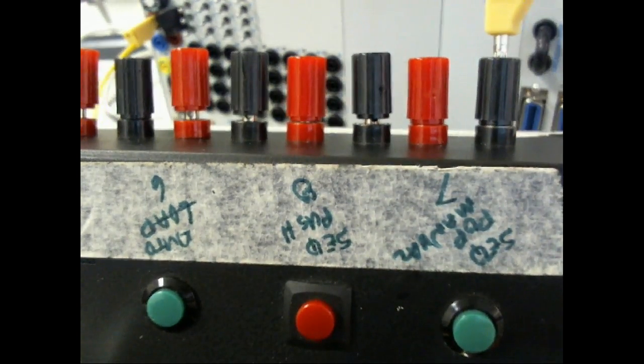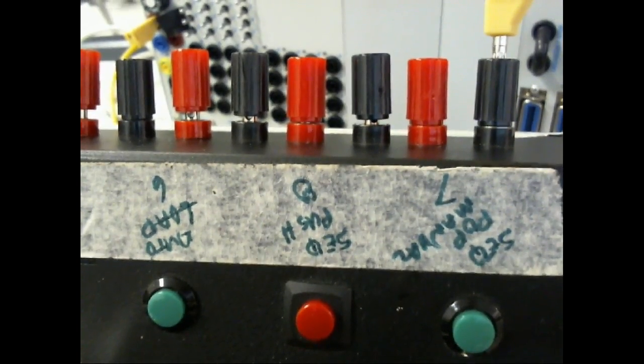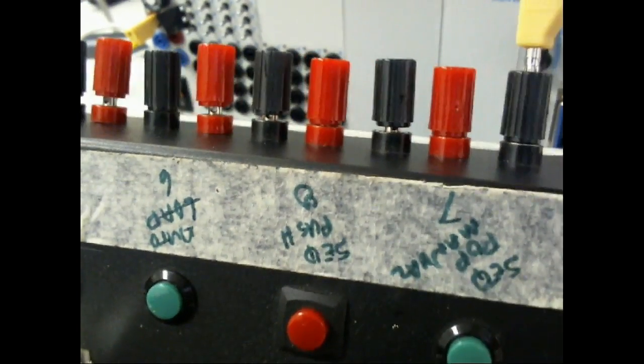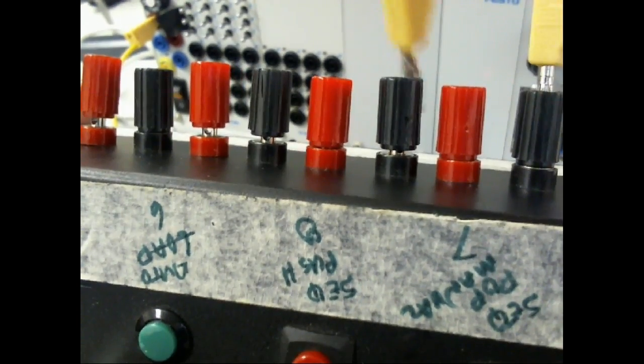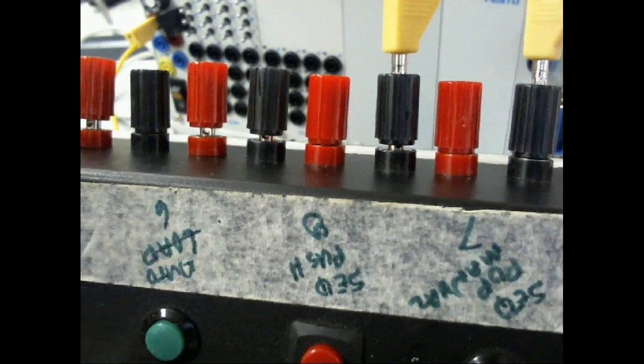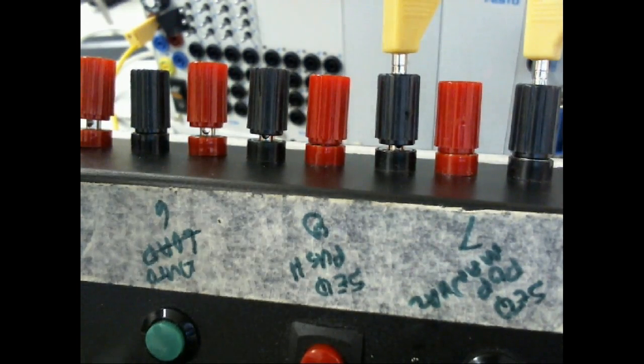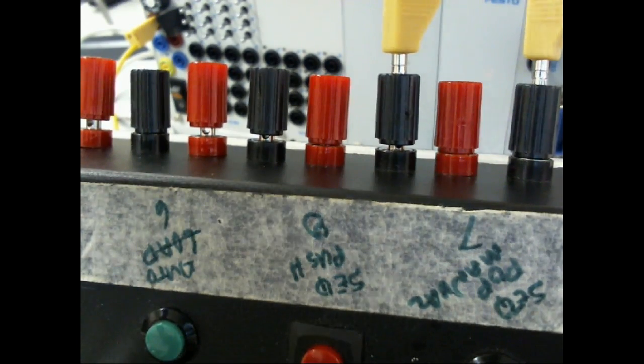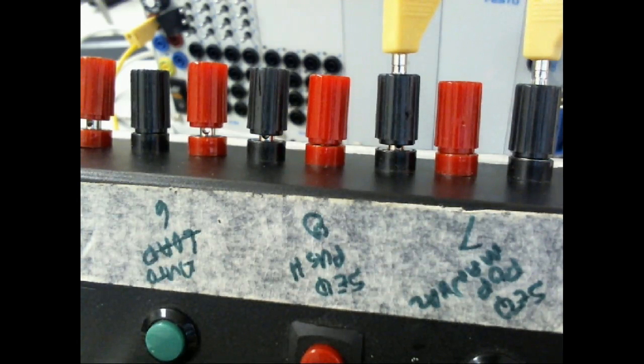And we got two push buttons. So what am I going to do? I'm going to just jump it over to what? To another push button. So all my input devices, if my input ports are set up to sink, right? You understand? So what I'm doing is I'm making the positive common for all my input devices. Okay?